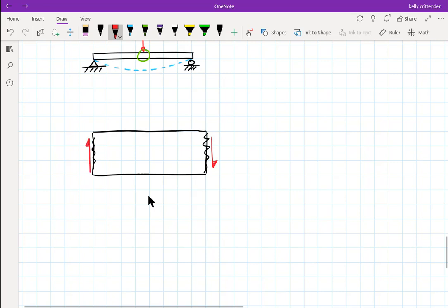If I put one way, then I have to put the other one the other way because I don't want it to actually shear. So I have to make these balance, right? And these can be shear force V. These two shear forces balance one another, so that this little piece, since I cut both ends of it off, has no reactions anywhere. I'm not looking at the pin or the roller. So these two forces have to balance one another so that the summation of forces in the y direction adds to 0 for this free body diagram.